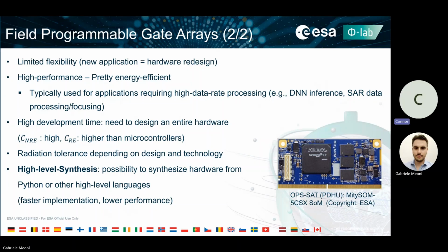It's possible to reduce the cost and the time. Nowadays, with what is called high-level synthesis, there are some tools that take your network and implement it for you, they create the hardware for you, so you don't need to design the hardware. Of course, you lose in performance, but you can really speed up the design. So FPGAs, that's why they become very interesting devices. However, the design flow is still way more complicated than for a microcontroller.